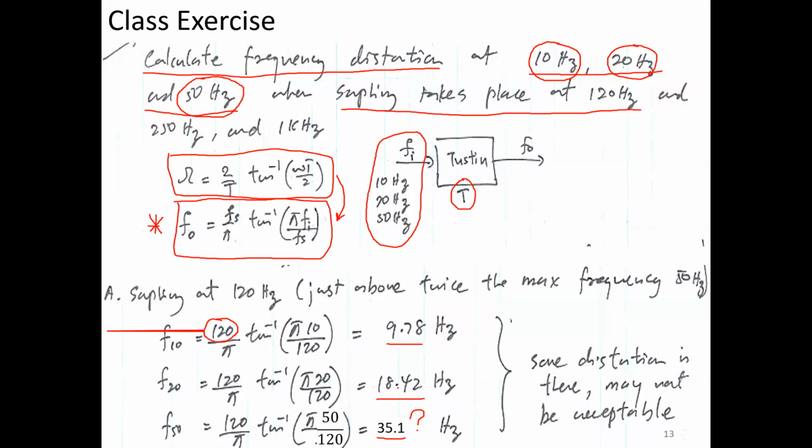So if you want to get 50 hertz back on track, just like 20 hertz here, you need to improve your sampling rate further up a few times. 120 is not enough, maybe 250 or even more, right? So generally speaking, when you select a sampler for a plant, you know your bandwidth and go for maybe 5-6 times higher than the bandwidth. So if the bandwidth is 10 hertz, your Nyquist says 20 hertz, but you go for 80 hertz, maybe, right?